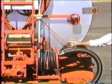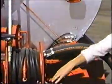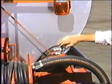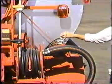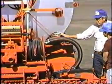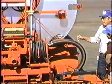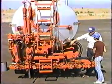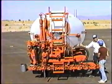On this particular machine, that valve is air operated. That is, we have an air control here that operates an air cylinder down here that will open that valve. When I pick that up, it opens the valve. When I put it down, it closes the valve. A little less expensive machine might have a handle out here, then instead of that nice air valve doing the work, you have to manually do it yourself to open and to close it. Also, we have available cab-controlled valve control where that cylinder would be operated by a solenoid valve up in the box and would be switched from the cab of the truck.